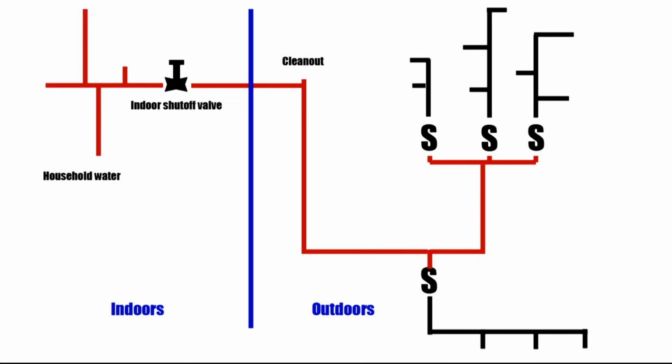Now here's a question for you. If really the problem is in a solenoid valve, why is it that only one sprinkler head is leaking? Why don't all three leak? Of course, the answer is that the piping in each zone is only charged with water when it's actively transmitting water. When those zones are quiescent, air replaces water, and so the pipes are largely replaced by air. Trickling down that air-filled pipe is a small stream of water, which always goes to the lowest point. And so what you find is that the lowest sprinkler head gets most of the excess water, and the upper two sprinkler heads get very little.